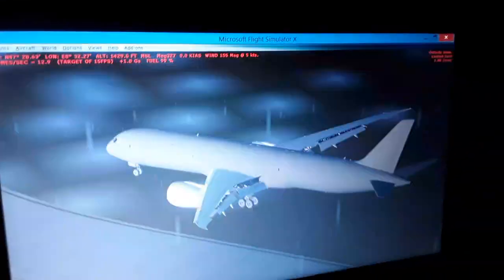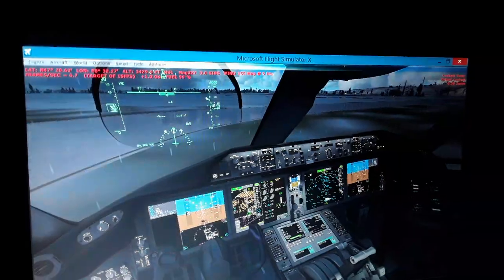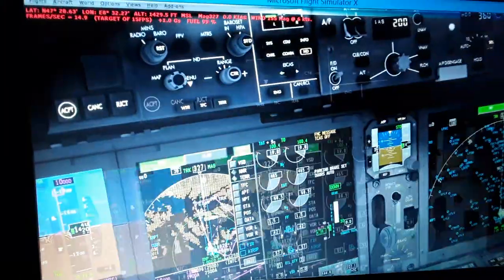So we're gonna use the runway 14 in the Zurich International Airport, where we are located right now, the LSZH, for takeoff and for landing both, and we can align with the magnetic north pole heading of 136 degrees for this reason. You're gonna see also we have the magnetic heading and track, the magnetic north pole and true north pole, and magnetic variation depending on where we are in the world.